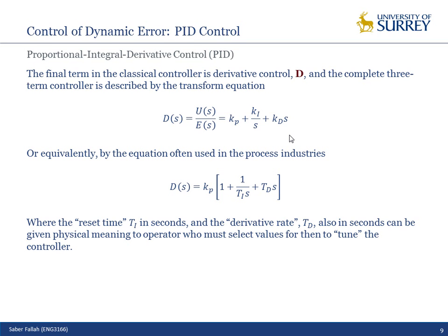The reason is that, look, assume I have just the derivative as an assumption, KDS, plant G(s), feedback error, R minus, plus 1. Assume in my feedback I have very high frequency noise, for example, noise N, 10 times less than the signal. So for example, 2 cosine 100t. Or let's say N equals 0.02 cosine 100t. Very small amplitude but high frequency.